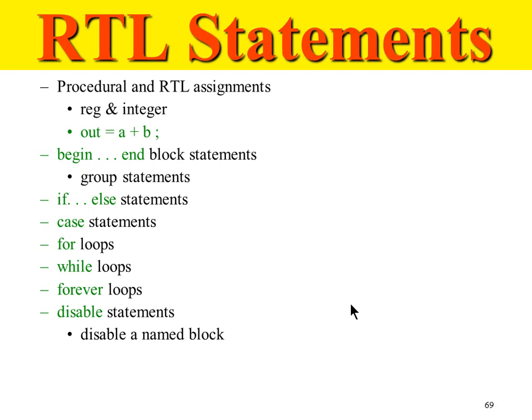So there are various things you can do with the RTL statements. There are various kinds of RTL statements, rather. There are procedural and RTL assignments. The assignments inside the procedural blocks, like out is equal to A plus B. This is one example. Then there are begin and end to create blocks of statements. So any always block or any initial block should have a begin and end.